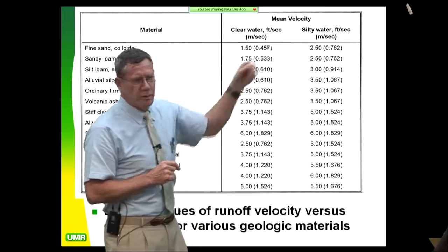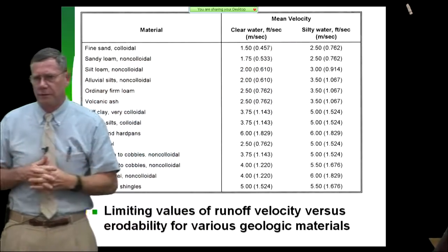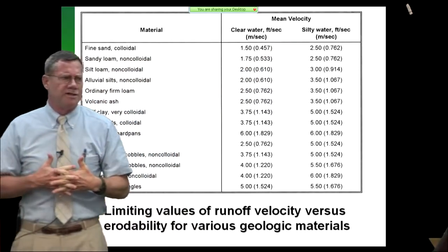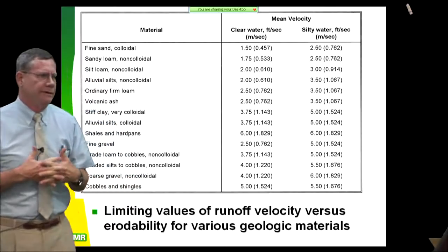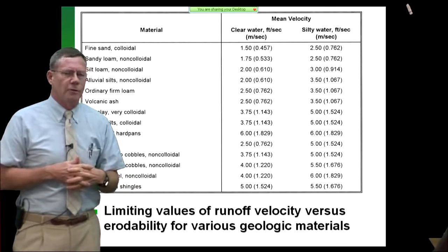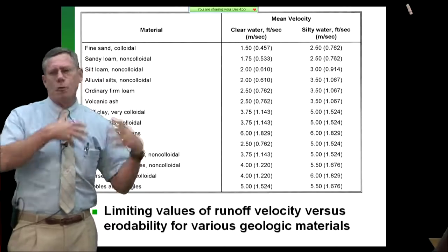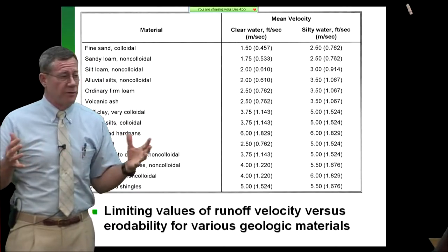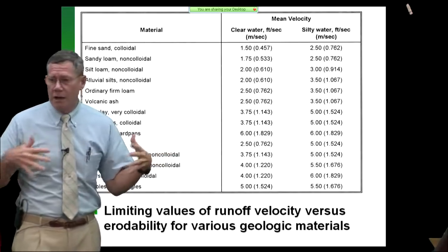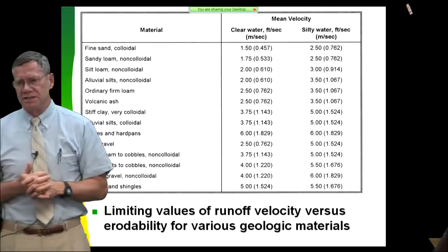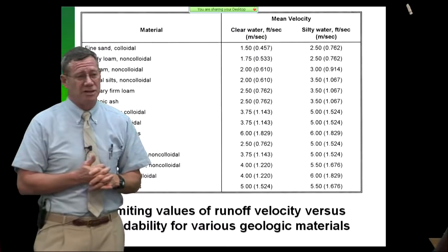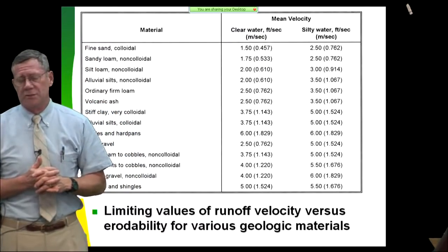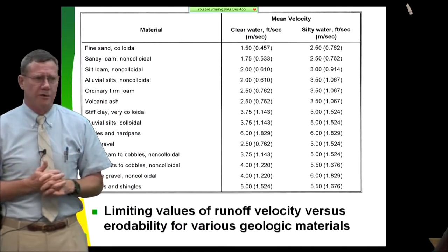Now when you have a storm and you go out there and watch the flow, which is highly instructive, you're always going to see turbid water. Generally you're going to see silty water, especially if you get out west of the 100th meridian, where we have a lot of erosion. So the Missouri River Basin only has 25% of the runoff that is contributed to the Mississippi River, but it has over 75% of the sediment load. So it's the muddy Missouri, no question about that.